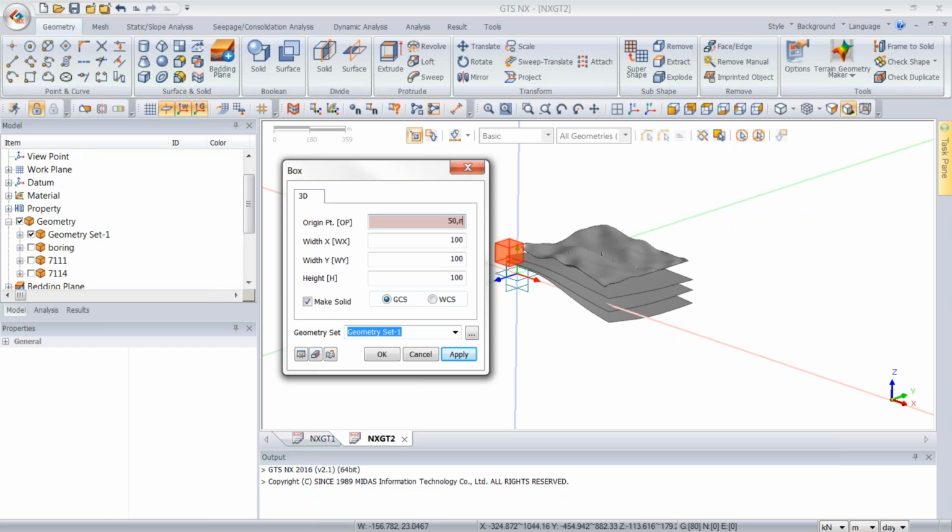You can do it with irregular geometries. You would just have to manually select the faces or the nodes to apply the boundary condition. But if you want to use the auto feature, then your model has to be a certain shape as far as the boundaries go. So this is why I'm using the cube. So here I'm giving it dimensions and locations. Of course, I can go here to preview, and I already know more or less what the dimensions need to be and where the origin needs to be.